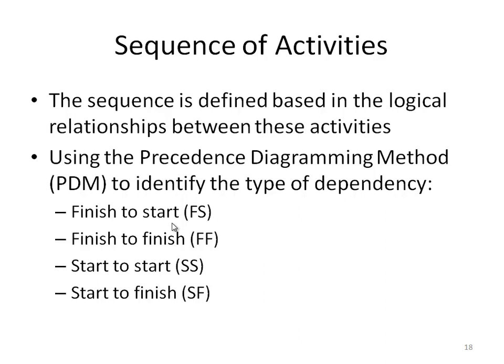Start to start means the initiation of the successor activity depends upon the initiation of the predecessor activity. Start to finish means that the completion of the successor activity depends upon the initiation of the predecessor activity.